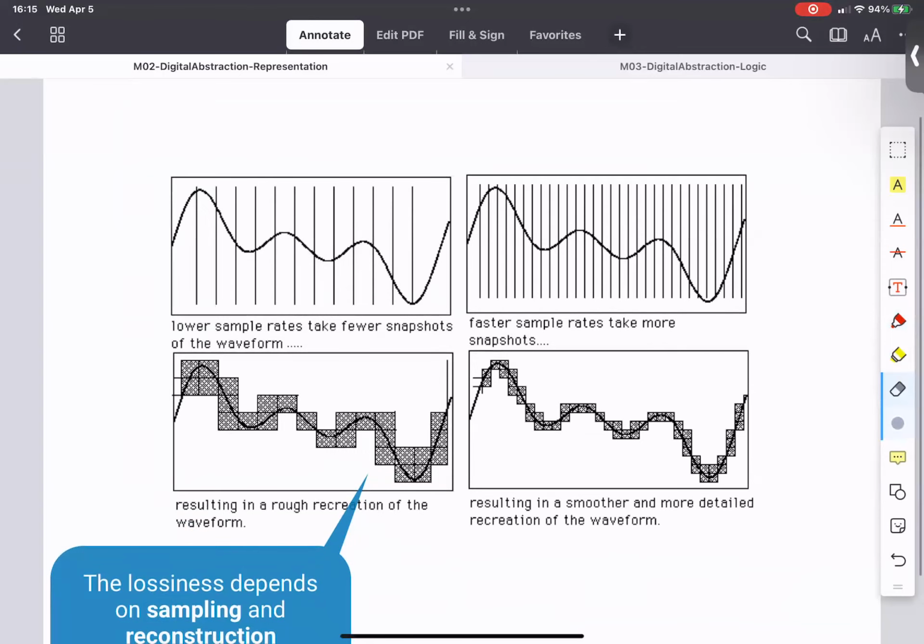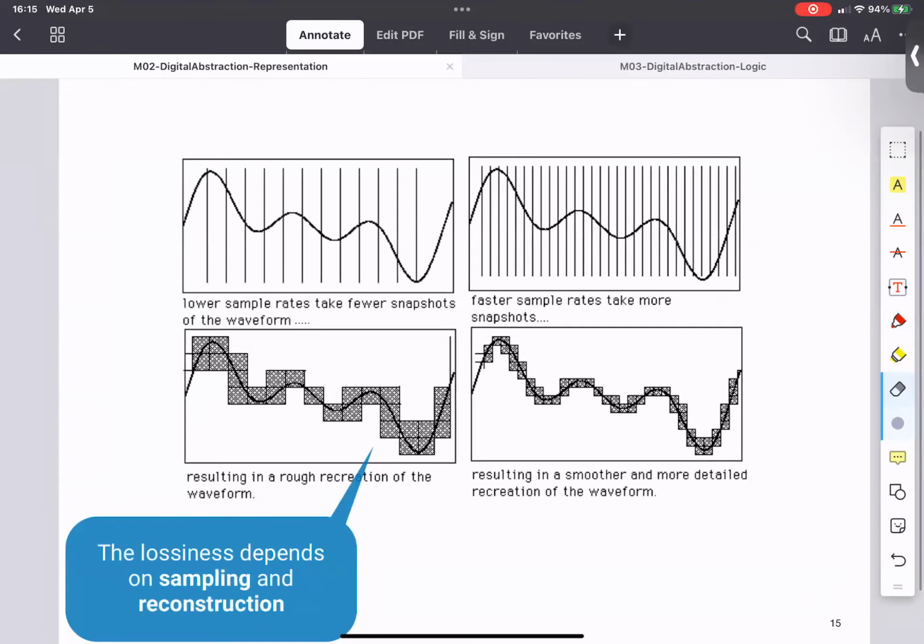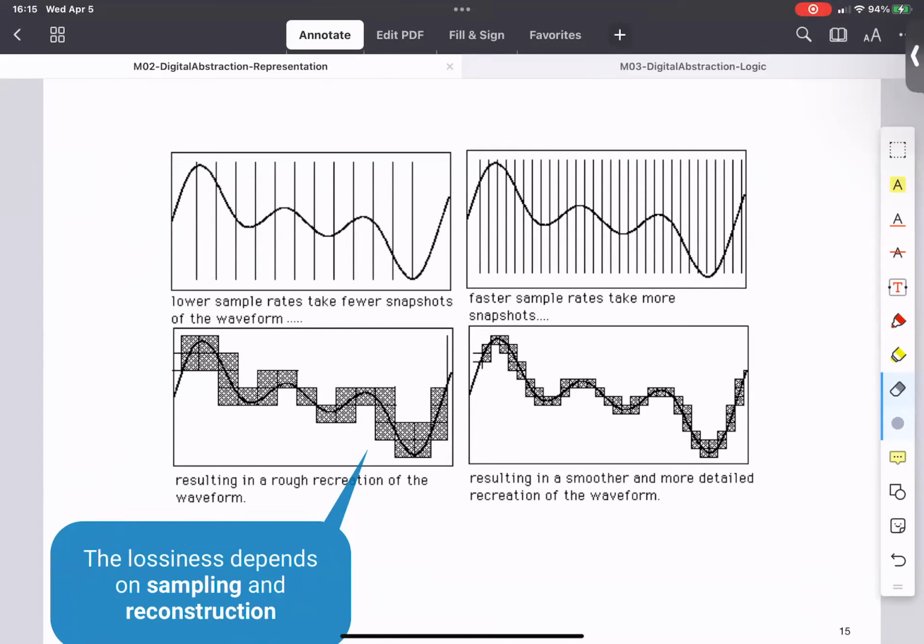Whenever we sample a signal in this manner, and sample some physical quantity in this manner, I need to have an associated way of reconstructing from those digital values. I give you a set of digital values, and in principle you reconstruct the original continuous waveform. So once I give you values at these time instants, you'll have a finite set of values, and each value itself, like this value out here, is discretized.